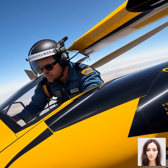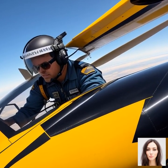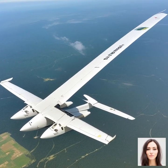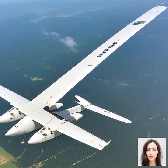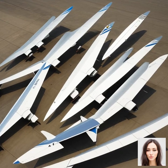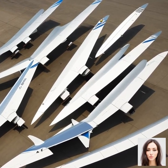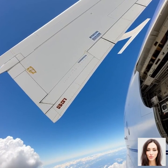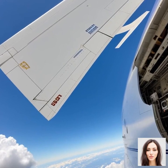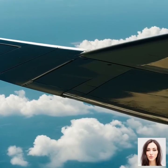An airfoil is the cross-sectional shape of a wing, and its design has a significant impact on the lift and drag generated during flight. A typical airfoil shape features a curved upper surface and a flatter lower surface. This design helps create the pressure difference we discussed earlier, which generates lift according to Bernoulli's principle. There are various types of airfoil designs, each with its unique characteristics suited for specific flight conditions and aircraft types.